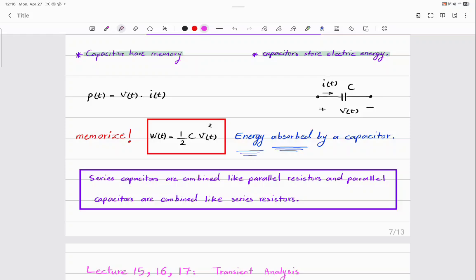Now, can you tell me in the next step, which is t equals 0 positive, what do you do to inductors or capacitors? Replace them with a source. Inductors with a current source and capacitors with a voltage source. And what is the value of the current source or voltage source? The value that you found for them in the previous step. What's the reason? Because they cannot change abruptly. Okay, I want you to know the process with the reasons so you won't forget them.